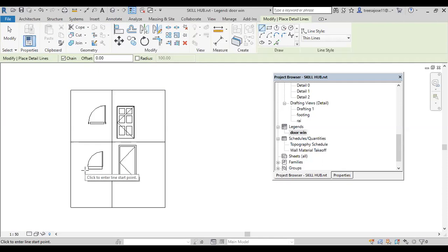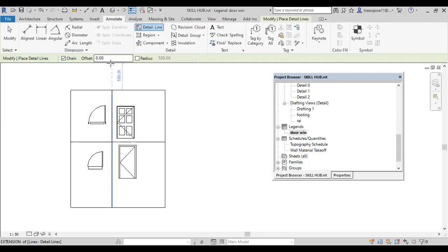Maybe you need to add the furniture legend into a different sheet because our complete project will include all these details. That time you can convert that into a different sheet. Okay, that time you can add the furniture legend. Here also you can add the furniture, doesn't matter. For example, the name of this legend is door and window. It doesn't mean that this legend will allow doors and windows only. You can add furniture details also here. Actually, the name doesn't make any sense, because while adding, if you put a proper name, it will be easier for us.